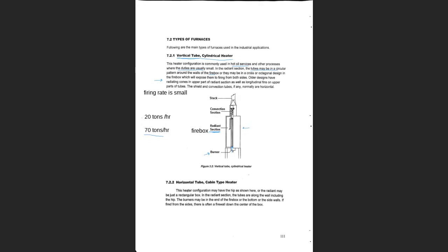So for the arrangement, guys, if this is the firebox as an example, the arrangement of the tubes is very important, in a way that we have to make sure of the burner locations if the burners are located here on the floor. By the way, guys, you'll see that the burners could be either floor burners or side burners, on the side wall.